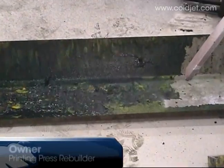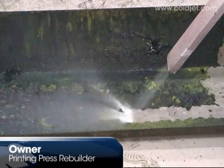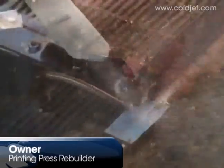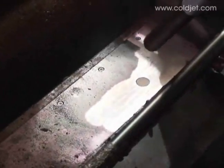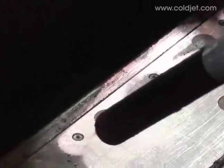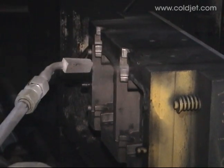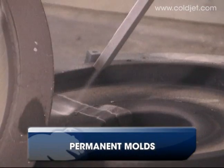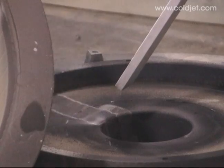Some of the ways that it's an advantage for us is, like I said, it's the solvents. The mechanics trying to use the solvents, which bothers their eyes, irritates their eyes and their nose, and also the cleanliness of it as far as using the dry ice. There's no carrying chemicals or using the wire brushes, and it's just a much more simpler, cleaner process for us. And in so doing, we've been able to reduce the amount of chemicals that we use. And that was a critical point for us, was to reduce our total air emissions and our hazardous waste stream.